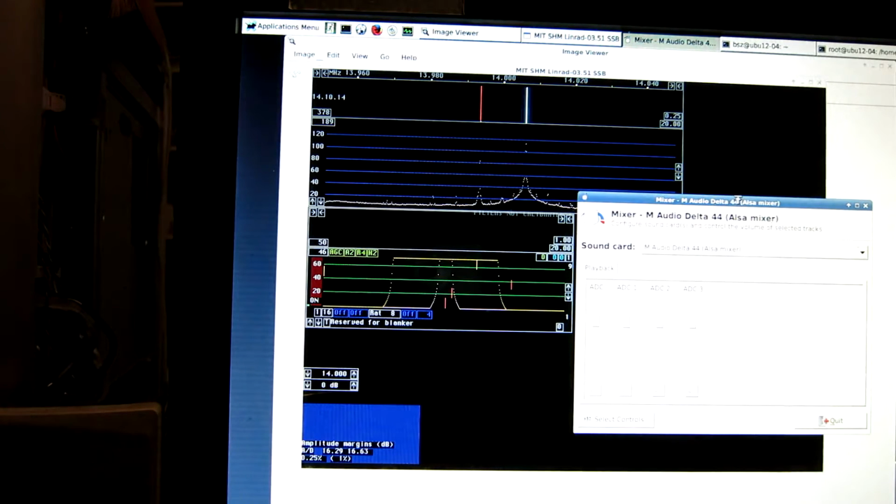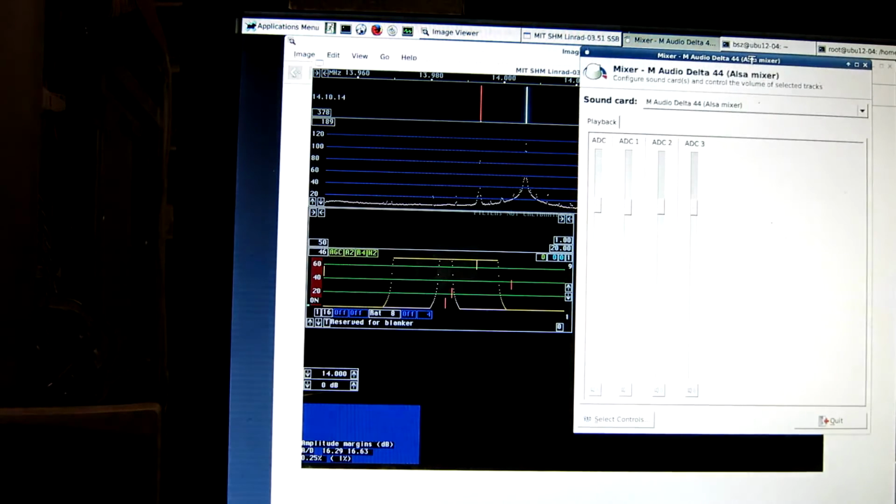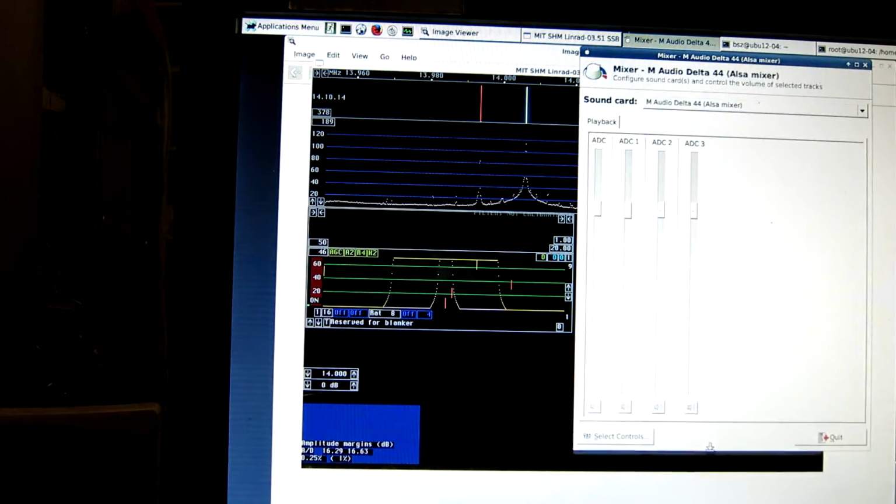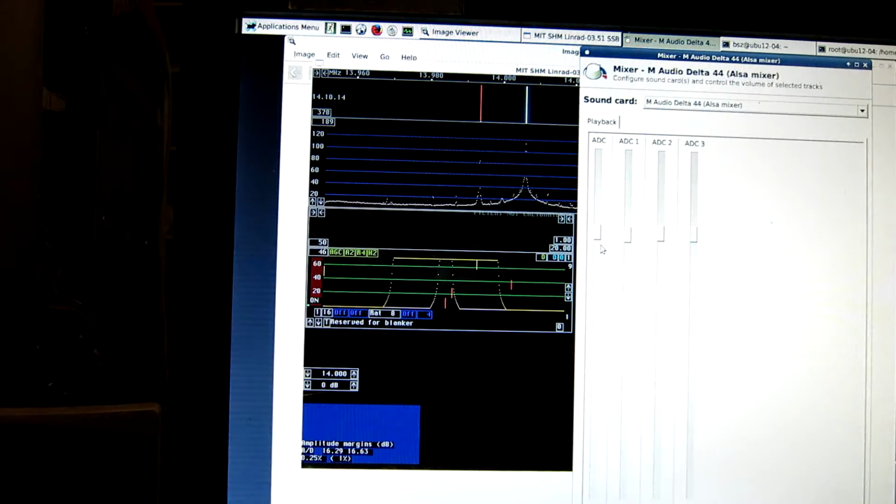Here, and to make it easier, magnify vertically, and then I can turn the controls up, and you see the mirror rejection becomes very bad because I bring up one channel but not the other, and I bring up the other channel as well, and here it looks good. So now the signal levels are the same.